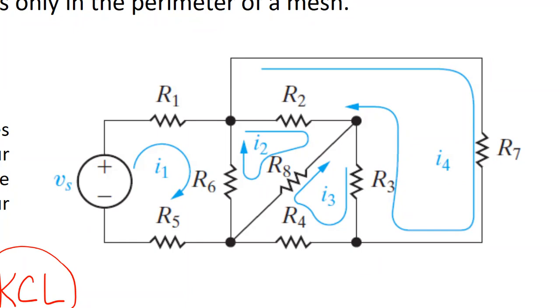Yes. Okay. Now we need to apply the formula, which says essential branches, which are 7, minus, in brackets, the essential nodes minus 1, closing the bracket. So the essential nodes are 4, minus 1, it will be 3, and then 7 minus 3 will be 4. So if we want to use mesh analysis, then we will have 4 meshes.